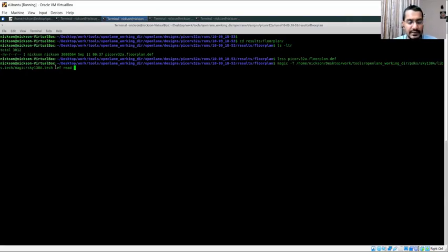So that is actually present inside the temp folder, which is 2 levels up. That means the temp folder is inside this folder. So we have to move 2 levels up. So we move 1 level up, 2nd level up, we do a temp, we do a merged.lef. So this is the lef file. And finally, we do def read. And this is the def file.